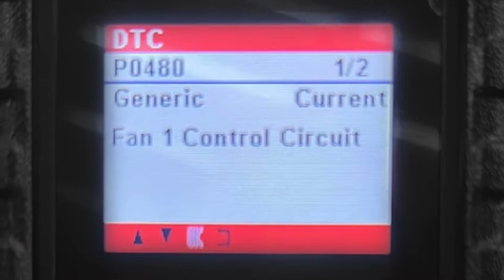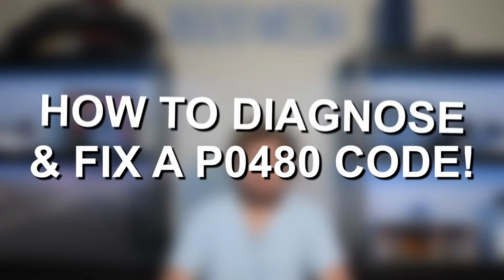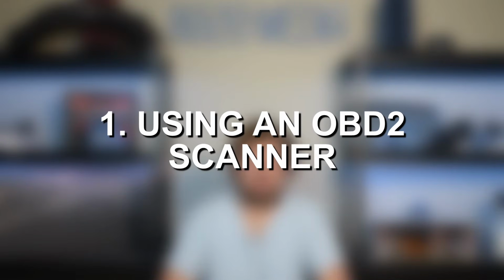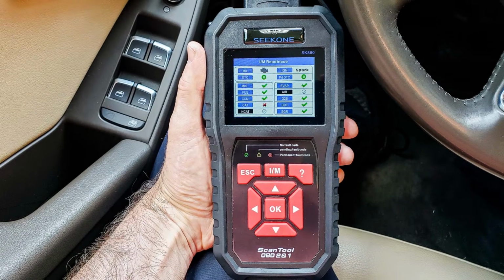So with those common causes out of the way, now that you know you have fault code P0480 and understand some of the common causes and symptoms, how do you actually diagnose this fault code and determine what is actually causing this issue? The best first step in diagnosing any issue is using an OBD2 scanner, hooking that up to the OBD2 port and reading any stored fault codes in the PCM.